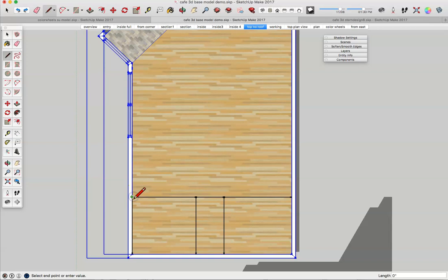So I'm going to go down here, 18. Just like AutoCAD, I can type in inches, and then I'm going to go across here. There. So that's filled in what will become my first wall. And so I'm going to come over here. I'm going to come over 6 inches. My typical interior walls are going to be 6 inches. Not that there's a lot of walls in this design.